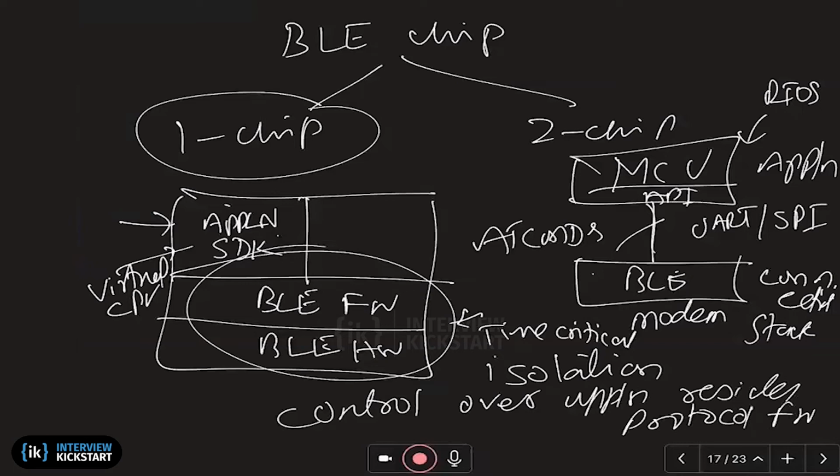So you need to have some kind of scheduling mechanism built into this chip. In the two chip case, it is hidden from you. You're having two separate processors, so there's physical CPU, two separate CPU. Here you're having a shared CPU. Therefore, if you are developing this product, you may use an RTOS of some kind or a hand-rolled scheduler, whichever you can, to separate the application from this.